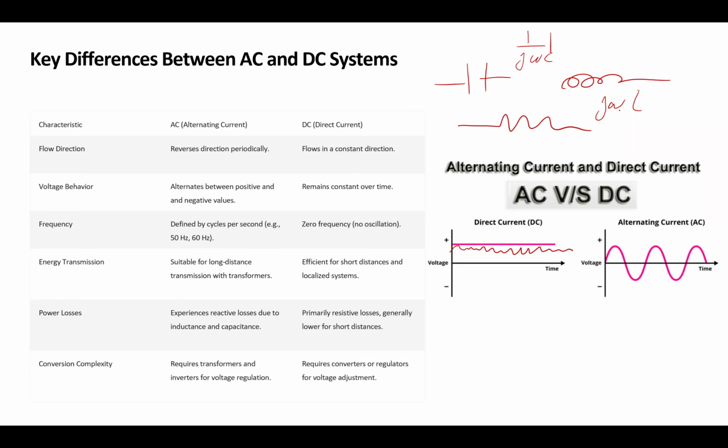Before, in DC, all the power that we generate would be active power and flow through the system. Now, because of that phase displacement, we have to spend a little bit, or a large amount depending on the phase displacement, of that energy we generated to deal with it, so we can transfer our power from source to load.